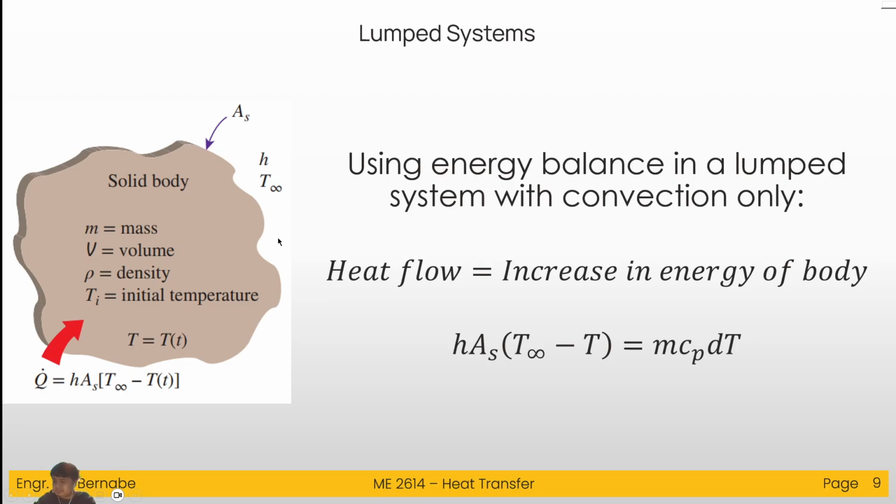And if it, for example, absorbs the heat through convective heat transfer, then it will store this energy within it. So the temperature will also increase. We can represent that as this equation using this energy balance: the heat through convection and then the energy stored. If we simplify this, actually this should have a dt in here.